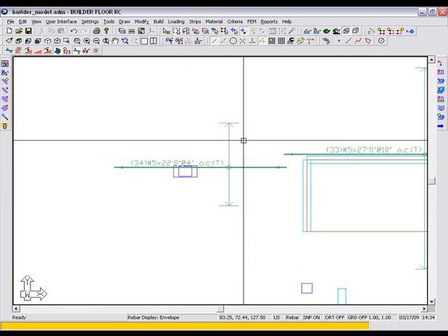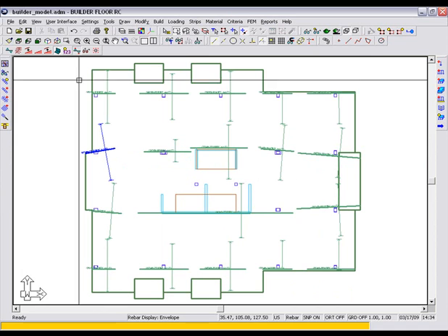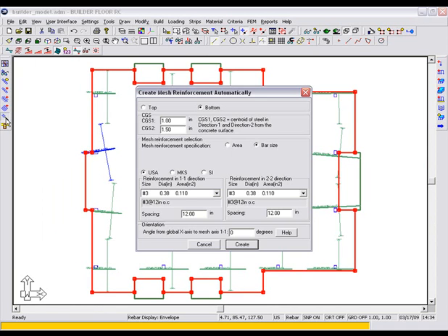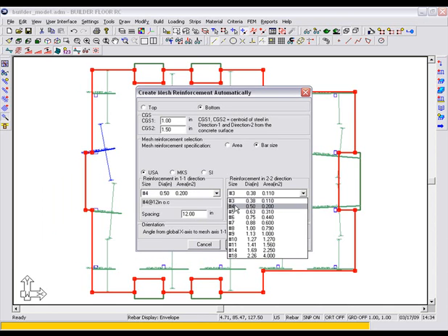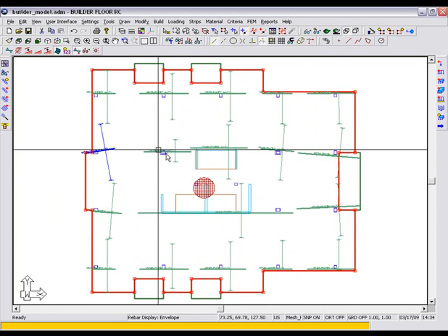We will now substitute some of the bars calculated with the typical base reinforcement mesh, which will reduce the total calculated bars. Let's add a top and bottom mesh of number 4s at 18 inches on center. We will then redesign and generate the rebar drawing. In this case, Builder will take into consideration the mesh created, therefore resulting in less overall reinforcement.